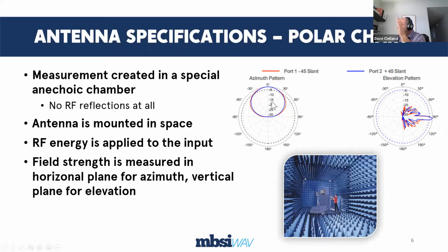We have 60 degrees in the horizontal, and we have 6 or 7 or 8 or whatever it is here in the vertical. Of course, if I blew up the chart, I could measure this much more accurately, but nevertheless, we have the same 2 patterns here. We have a left slant and a right slant, and they're both slightly different, but overall, the patterns are more or less the same. You can see here that in the positive slant we have, again, a little bit more attenuation than what we have in the negative slant, and that's probably due to construction technique of the antenna.